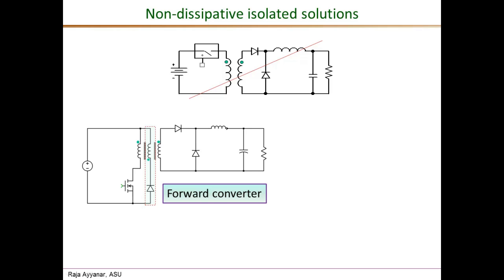The mechanism of flux continuity. When the primary side switch is turned off, the magnetizing current, which was responsible for the flux, was entering the dot. Okay? So all we need is a current in any other winding that enters the dot. In the secondary side, that is not possible because of this diode. Whereas here, this is called the reset winding, the diode is connected with the correct polarity to support a current that enters the dot at this point.